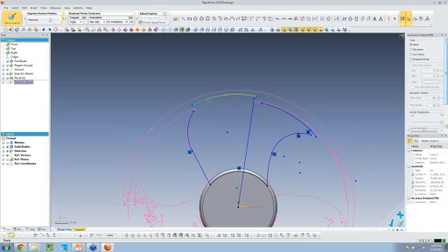And what I'd like to do is grab a hold of this one as well, and maybe move that around a little bit. You can see that center line point. Maybe I want that to be concentric to the center line axis of the part. So I want this outer to be concentric. So I just pulled its arc center point and snapped it to the center. Now I can start doing my final trim, and now I'll have my final profile.